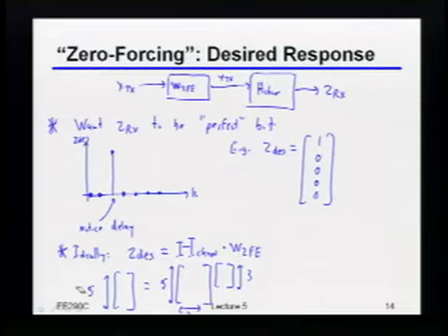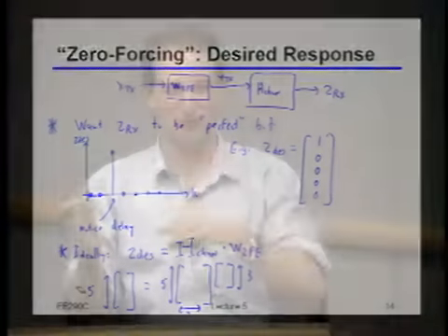If you're talking about estimating what the coefficient values are, then once you're getting to the receiver or sending information back to the transmitter, the way you typically do that is indeed relative. If you know where your cursor is, or you just assume that you are at the right spot, then you figure everything out relative to that cursor. So you'd say the precursor needs to be this, and the postcursor needs to be that, and so on and so forth. Is there a question in the back?